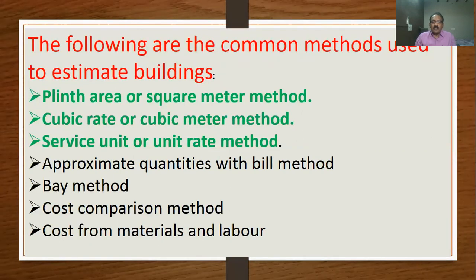Say you want to construct a hospital building for one bed. What is the cost of the building? Like that, unit service. Similarly, hostels, auditoriums. That is the unit rate method.